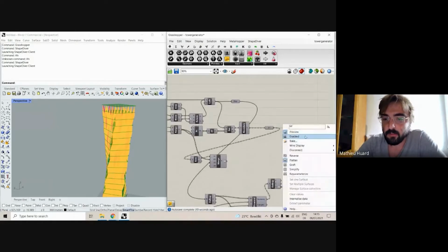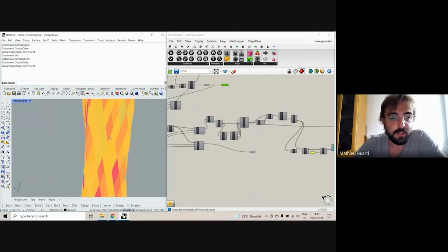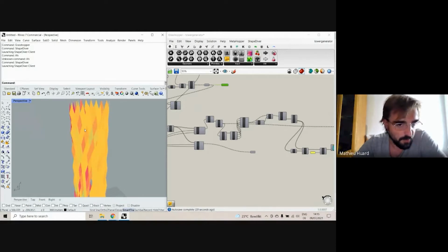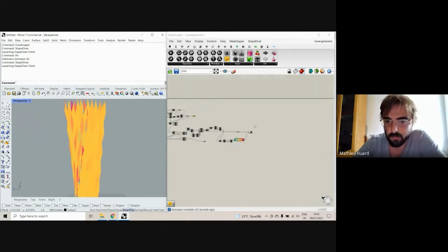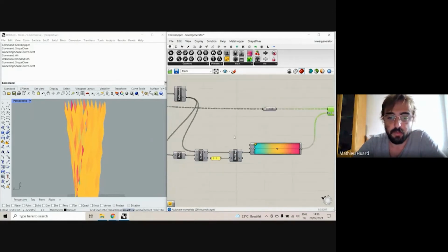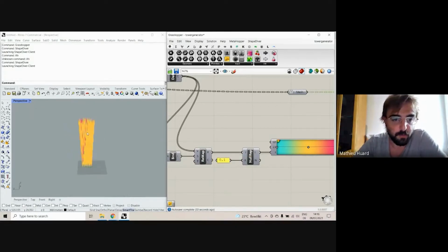The definition also contains a quick check of how planar each of the panels is and how far they are from being planar, and applies mesh colors to each of the panels. Each of the panels here is a separate mesh, and there's a gradient according to the unitized value of the measure of planarity for each panel.